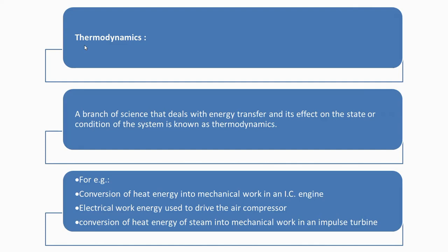It compresses that air, and then it is stored in the receiver, and it can be used for various purposes like filling air in the tire tube, for pneumatic activation or pneumatic cylinders, then the pneumatic hammer, air motors, etc. So here also the energy transfer, electrical energy, is transferred into the motion of the piston inside the cylinder with the help of, again, a single slider crank mechanism.